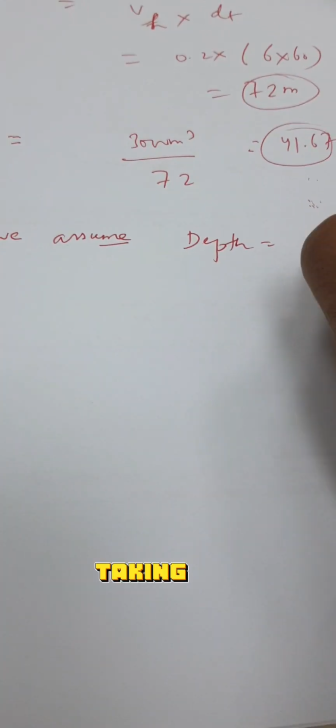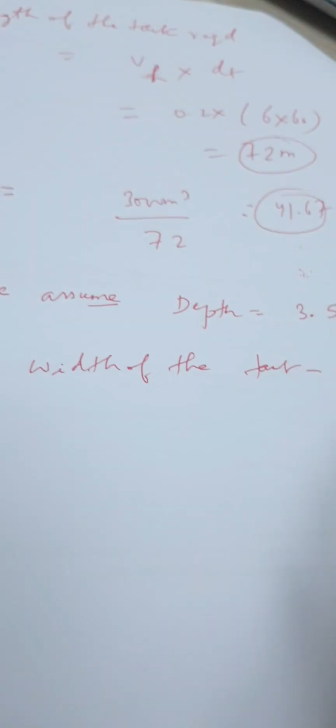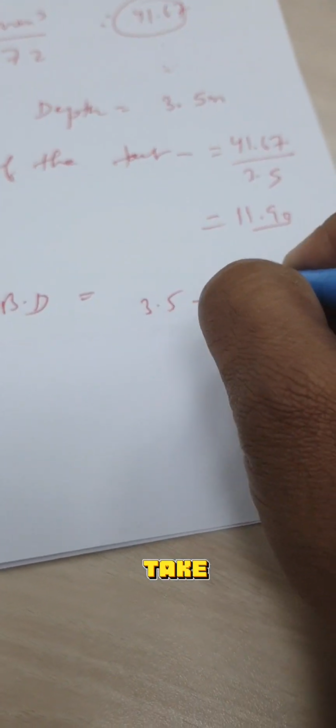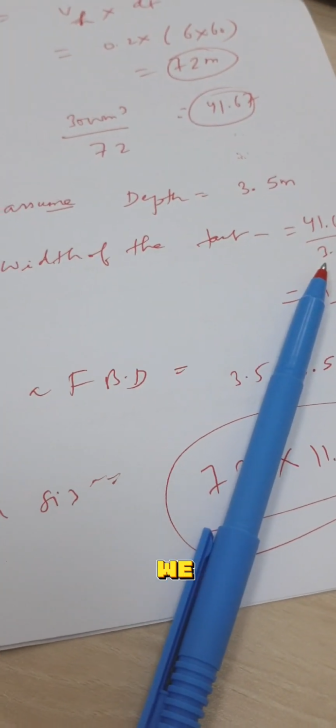Now suppose we take the depth as 3.5 meters, so the width of the tank is equal to 41.67 upon 3.5, which is equal to 11.90. And then we can add a free board in depth. We have taken 3.5, and if we take 0.5 meter of free board, it will be equal to 4 meters. And then the overall size is equal to 72 multiplied by 11.9 multiplied by 4. So this is my final dimension of the sedimentation tank that we are going to design.